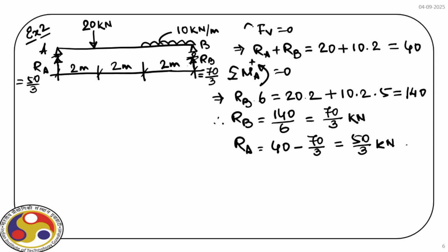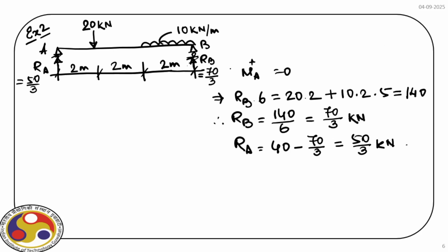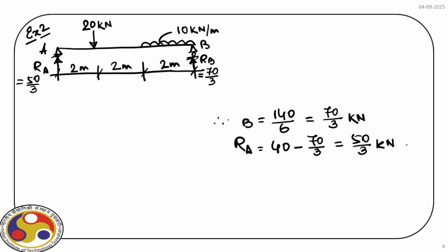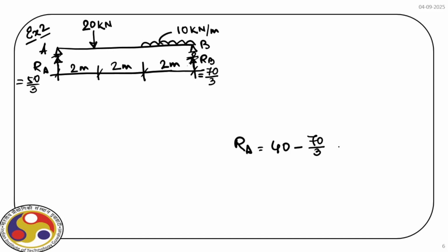Right? Okay. So next we will find out the moment at a section X from the left hand. And what we'll do, we'll consider both the loads and we'll take the section at a distance X from the left hand so that it covers the complete domain. So for that, we consider a section here.